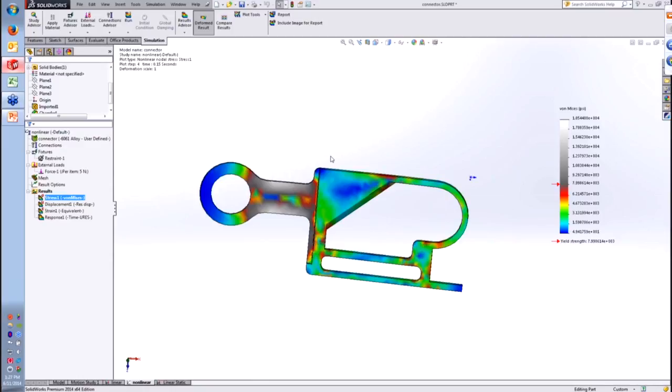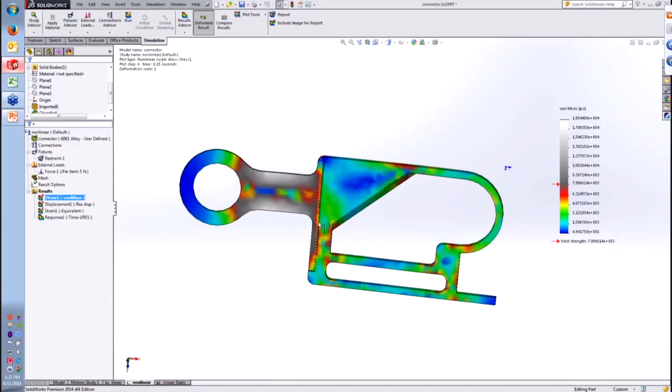And then we get our results. So let's look at the stress plot this time. Here we're seeing that the maximum stress is about 1.85 times 10 to the 4th psi. So we are almost an order of magnitude lower than the maximum stress that the linear study predicted. We're also showing, again, that option where any of the areas of the part above yield are shown in gray.